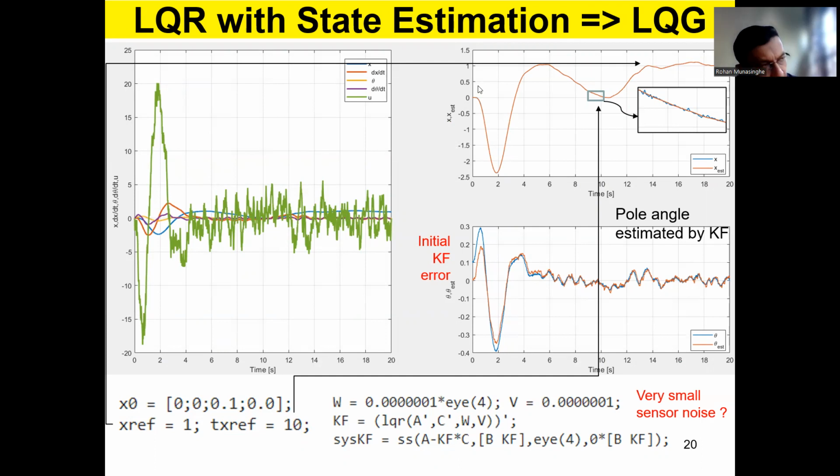Now, what we do now is that we understand that measuring only the cart's position is not adequate, okay? You need to measure the pole angle also. So let's add a rotary encoder to the pole and try to measure the angle, right? Now you have the position and angle both. So I think we can expect a better performance, right?